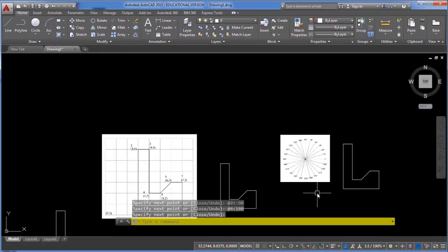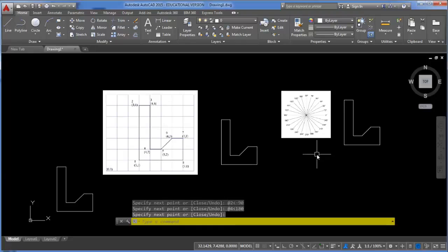So as you can see, 3 different methods for drawing the same exact shape. Still, they're fairly basic shapes, and in AutoCAD, we will learn more advanced features that allow us to do that even quicker. But I will say I always revert back to these in certain situations, especially the relative when I am drawing a rectangle, as we'll see later. And then also, anytime I'm drawing lines at a weird angle, I always use the relative polar coordinate method. So it's just a matter of getting used to these 3 methods and picking and choosing when they will work best for you.